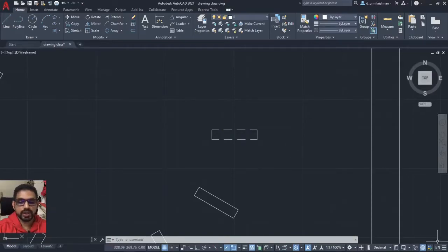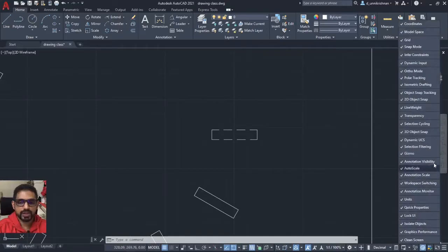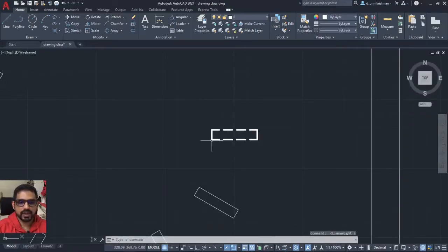What generally I would do is go into the bottom right corner that you can see here, customization, which I had mentioned a few videos back. Click on it and make sure that your line weight is ticked. Okay, so I'll untick and I'll tick it again. As you can see here, this particular icon popped up. So this is the line weight to be displayed or not. So clicking on that, yes, now I can see that this is a thick line.